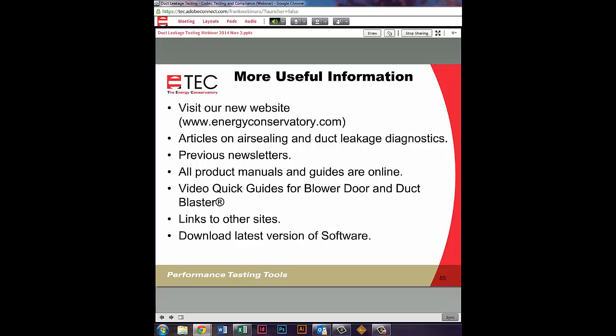Let's see. One of the questions is, would you also want to seal the inner jacket of the flex duct before you install mastic on the outer insulation of the jacket? And certainly, yes, that's something we want to make sure of. With the tie strap tightening tool, a lot of guys will try and tighten it by hand, but certainly you want to do a mechanical way to tighten that as much as possible. Once you've gotten that tight, then just doing mastic to the outside is all that's really necessary.